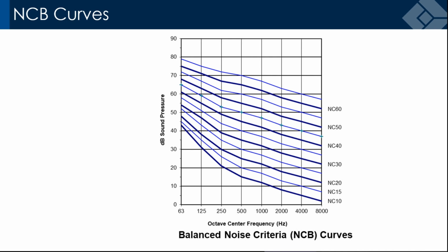And this is an example of a service we offer. This is an acoustical generator, natural gas powered. I think this one was maybe about 4 megawatts. It has a noise level so low that it meets Illinois Title 35 compliance, because that picket fence is the fence of the mother of an attorney who understood Illinois Title 35 and how super restrictive it was. And this thing passed with no problems. In fact, we had to have people turn off their cars idling 50 yards away because we couldn't measure any noise from it. So it is a service that IMEG offers, designing really high attenuation emergency generator enclosures.